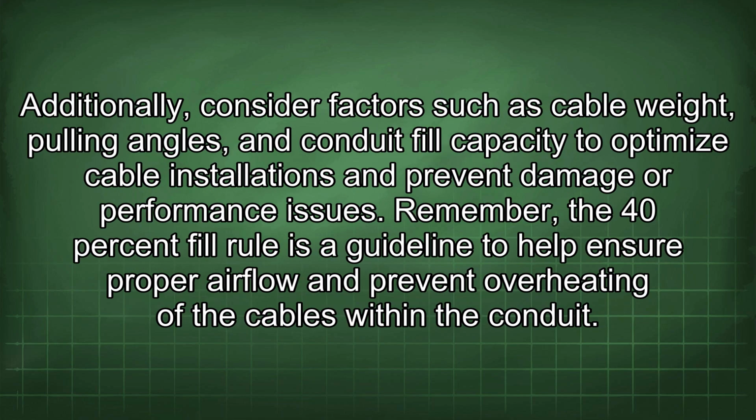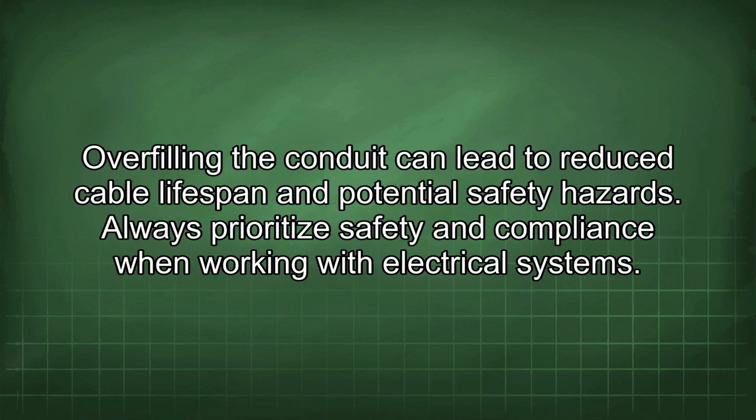Additionally, consider factors such as cable weight, pulling angles, and conduit fill capacity to optimize cable installations and prevent damage or performance issues. Remember, the 40% fill rule is a guideline to help ensure proper airflow and prevent overheating of the cables within the conduit. Overfilling the conduit can lead to reduced cable lifespan and potential safety hazards. Always prioritize safety and compliance when working with electrical systems.